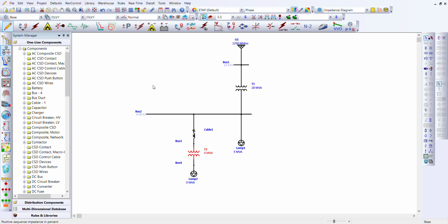Now, the function of this typical is to automatically generate calculations that will produce the automatic values required for the rating of the transformer you have set as 1 MVA. Now watch this. If I put typical impedance, this is typical Z and X over R, with typical impedance and XR ratio. So once I click it, the values are automatically there for the transformer. So you don't actually have to stress yourself calculating the impedance and the XR ratio. Once you click on it, everything pops up. So basically we are done with the setting of the transformer for now.